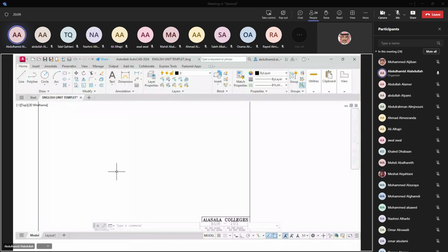We used it as geometry, which is typing the entire name, which is line, or another way, which is typing only the command or shortcut, which is the letter L. Just by typing L and then enter, right away it will give me the line function where I can start drawing using line.